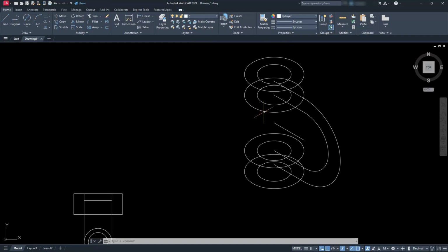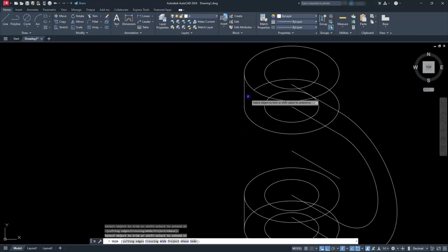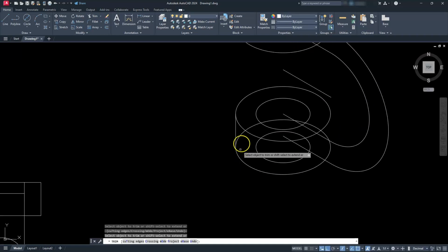Another thing that I can go ahead and do is get rid of the vanishing edges, meaning that I can draw a line now, and I should have some quadrants show up at the vanishing edge. So I'm going to click here, then I'm just going to go straight up and click at this quadrant here. Let's go ahead and trim off this portion. So I'm going to trim between here. Let's zoom into here, and I'm going to start trimming off right around this bottom circle. And I'm going to stop here because I don't know where this bar here in the front is going to lie. And I'll do the same here at the bottom. So I'm just going to trim this portion off here. All right, and that's a good place to stop on here.